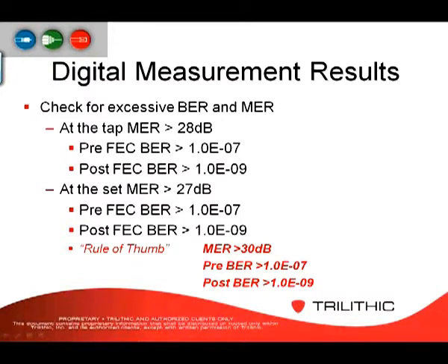For your posts, you always want it to make all of the corrections. That's after the forward error correction is kicked in, you want it to be able to correct any errors. So you always want that at a -0.9 or greater.